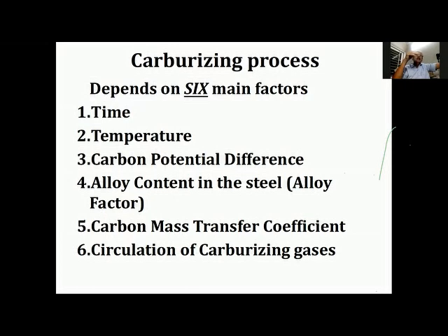That means if you increase the carburizing temperature a little bit, the depth will go up on a very high scale. At the same time, the control of the process becomes difficult. That's why if you have got shallow cases like 0.2 to 0.5, temperature used will be less, where you can have very good control of the case depth.